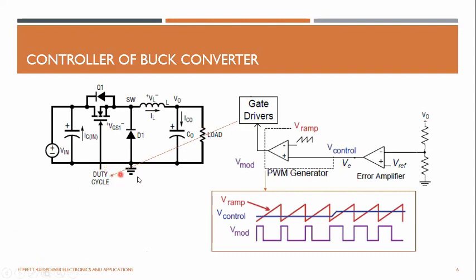Right, so this comes with the gate driver. A gate driver is simply an IC like this. It takes a power supply to power up, and from any Arduino or microcontroller, a signal can be driven to the gate driver, and the gate driver will then drive this MOSFET, right?